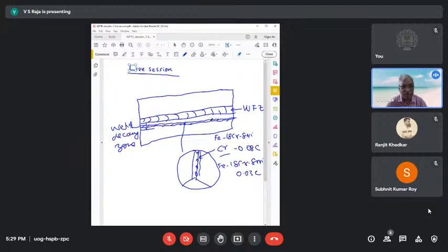So the so-called heat affected zone here, we call the weld decay zone. The way it is corroding is independent of the filler wire that you choose here, what consumable you are going to use here. Of course, if you choose a consumable that leads to a change in thermal cycle, it's a different story altogether. So it is independent of this. Of course, when you talk about choosing a filler wire, there are also regulations and guidelines on what filler wire to choose.